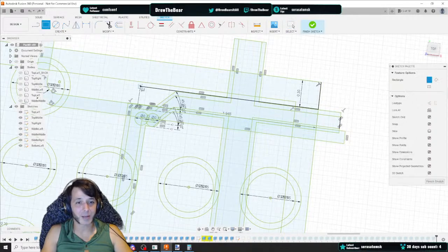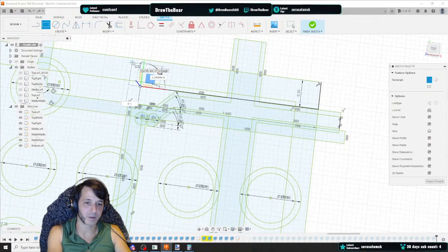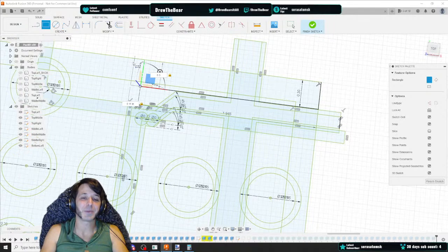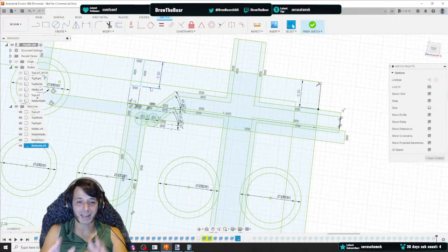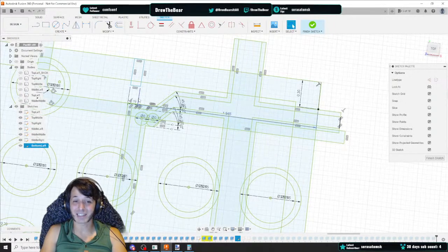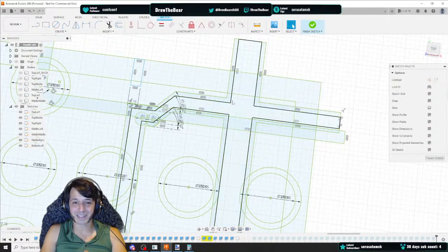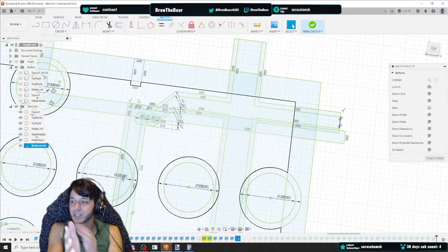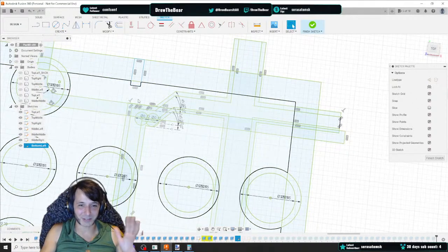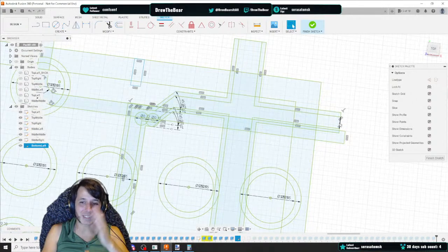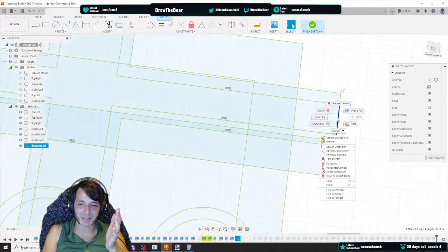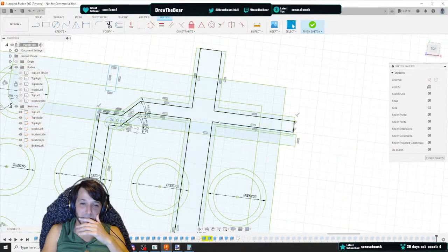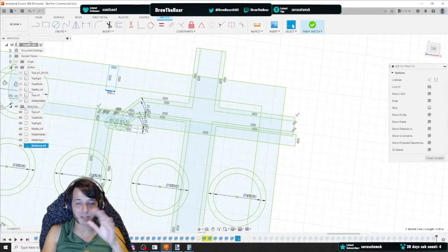Okay, sorry, I made it 0.1 width instead of 0.11. It needs to be 0.11 because the rod is 0.1 and PLA, the plastic I'm using, expands slightly, which means I need to make the hole slightly larger than the rod it slides into. God, it's all so confusing. It would take me days to explain this project to somebody. Multiple days. Okay, so now it's 0.11.